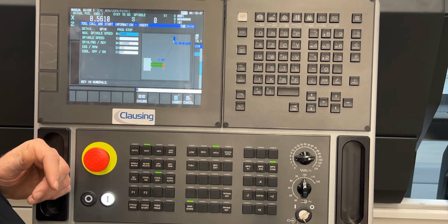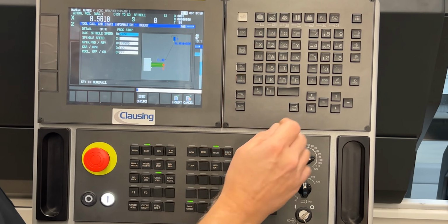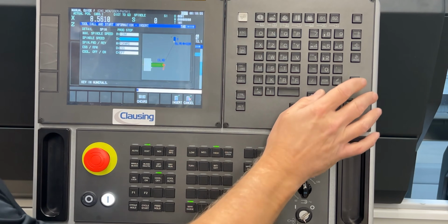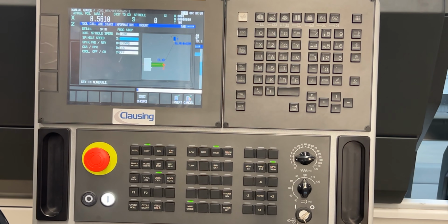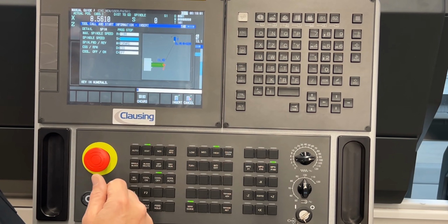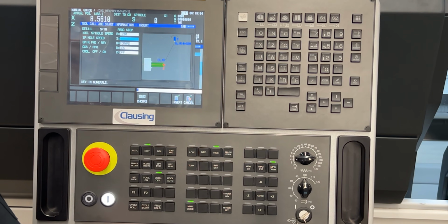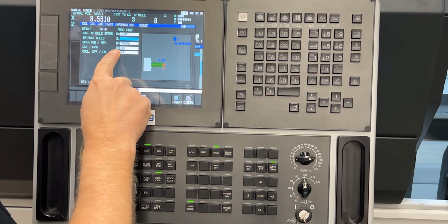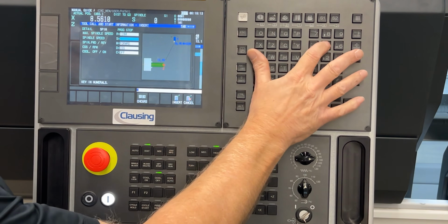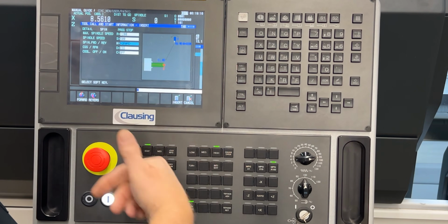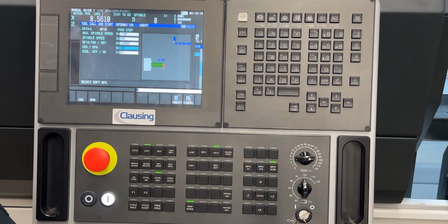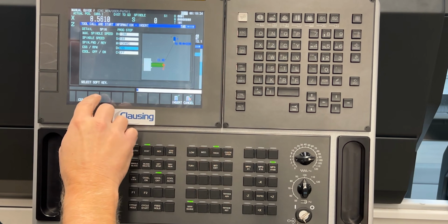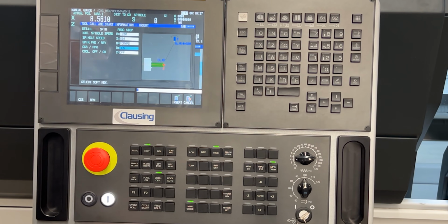The first thing on there is the max spindle speed. What do you want to set it to? If I put in there 1200 RPM, that will be the max spindle speed if I'm running CSS. The spindle speed value we're going to put in is all determined by whether I'm working with CSS or direct RPM. So if I put in there 500, in the forward direction, and if I have CSS active, then it will be 500 surface feet per minute. If I have RPM active, then it'll be 500 RPM.